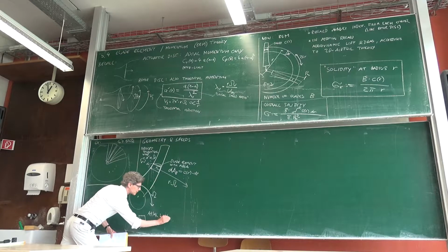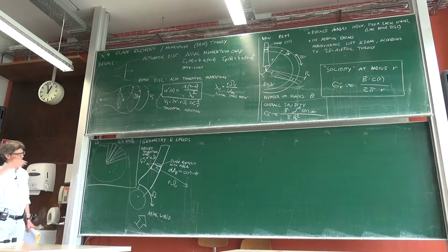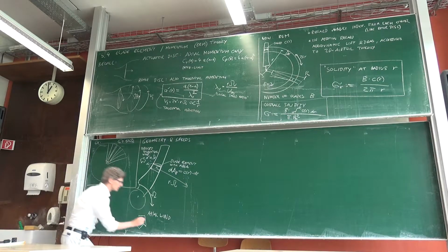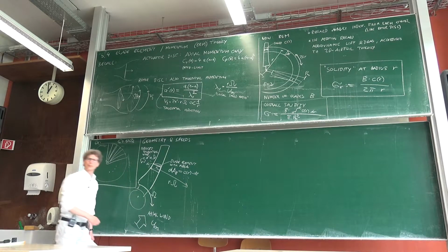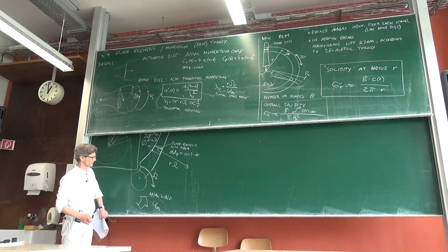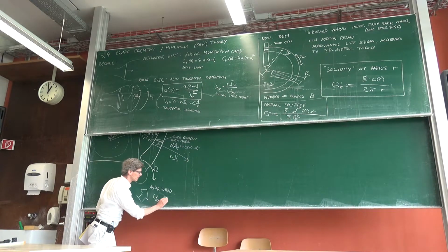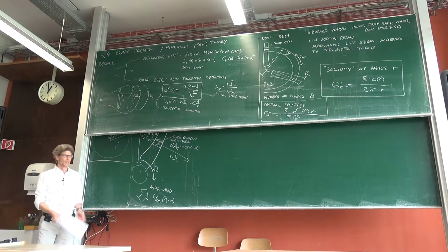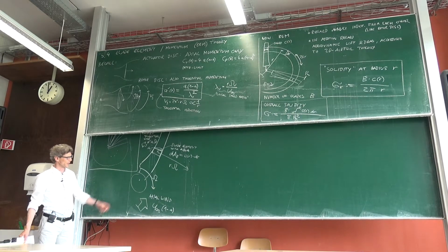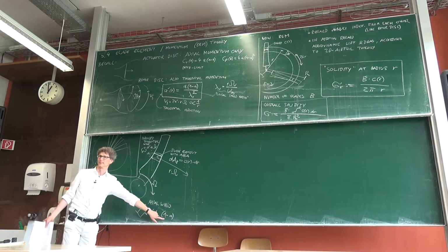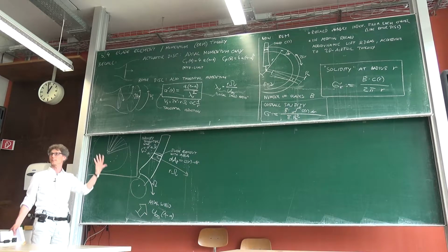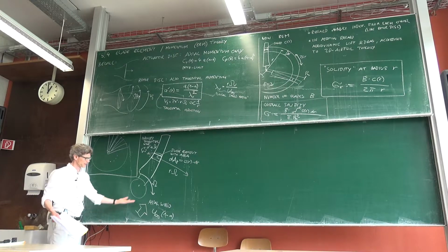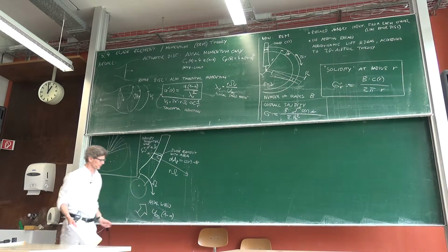And what would be the axial wind in the direction that flows through the plane using induction factors? It's u infinity, our free stream velocity, times 1 minus a. That was the definition of induction factor. And I don't specify what values a prime and a have now. I don't know it actually because it depends on how much force the blade will exert on the flow. But I know that there will be this induction.